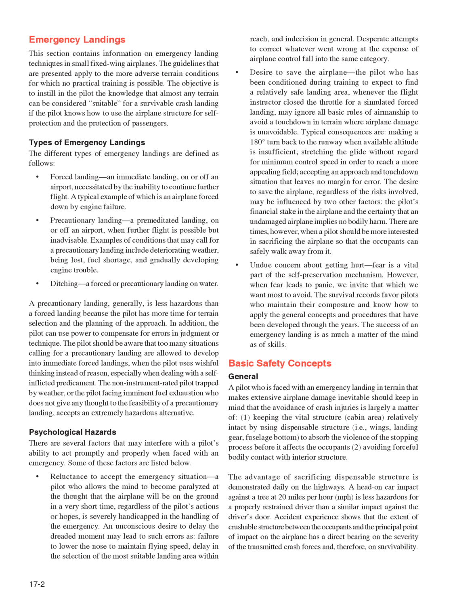Keeping the vital structure, the cabin area, relatively intact by using dispensable structure, i.e., wings, landing gear, and fuselage bottom, to absorb the violence of the stopping process before it affects the occupants. 2. Avoiding forceful bodily contact with interior structure.